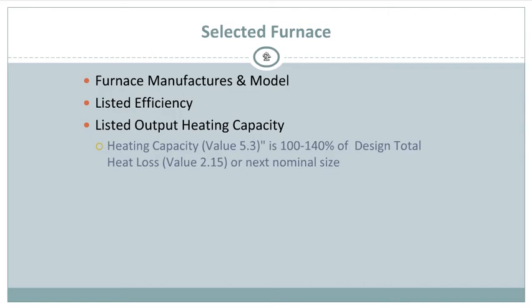Okay, so again, it's going to list the efficiency as when you bought it. It'll say 85, 91. Once you get into the 90s, 90% efficiency and up to 95, those are what they call your high energy efficient furnaces. These are going to take special installers. You have to have a contractor that's licensed both in gas and in electric, okay? You're going to need a plumber and an electrician in order to install these units, because the high energy efficient furnaces are going to take a lot more gas.